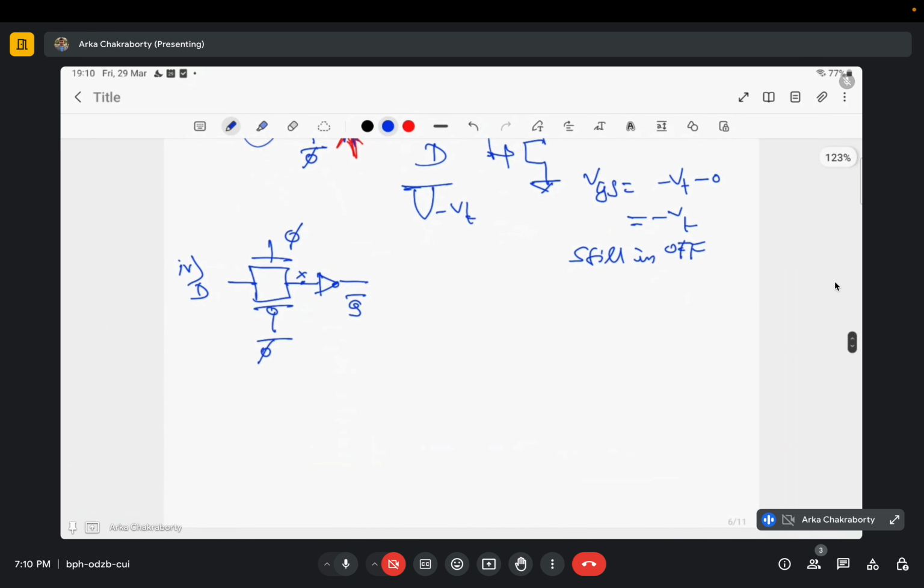Now, whenever we bring a CMOS circuit like an inverter or buffer, you will remember that the noise problem generally vanishes, because inverters have rail to rail swing. So from seeing also, you can say that it is insensitive to output noise and only sensitive to input noise. But let us look into it.